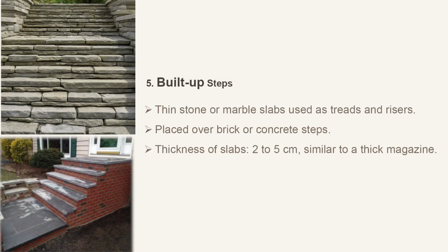Built-up steps. In these, thin stones or marble slabs are used as treads and risers, placed over brick or concrete steps. The thickness of these slabs ranges from 2 to 5 cm, kind of like a thick magazine.